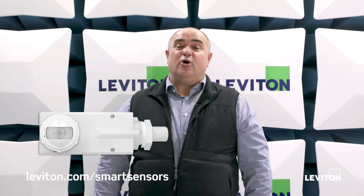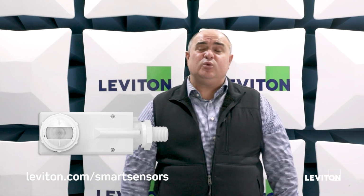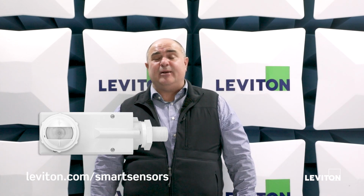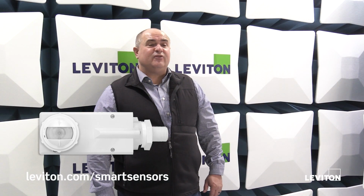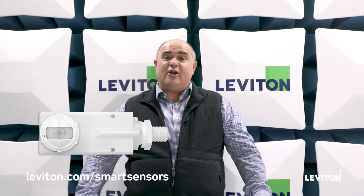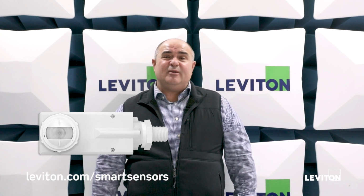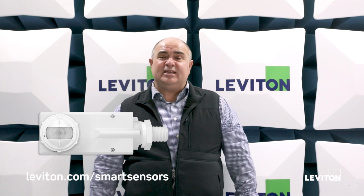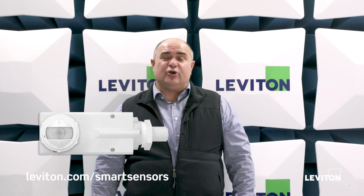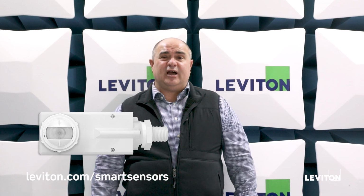You say, well, what would the code requirements be in the parking lot area? Well, again, most of the codes, Title 24, as well as some of the other codes, will allow you to pair up to 1,500 watts of lighting together as a common zone. So you can pair up to 16 of these devices on individual fixtures and again be able to respond to a common schedule that is in one of them and have all of these lights turn on at the correct time as well as turn off at the correct time.